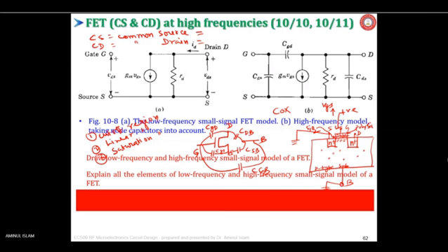If the gate voltage is 0, instead of some positive voltage, then there is no inversion layer, this layer of electrons as you can see here. The layer of electrons gathered under the gate is not there, so current cannot flow from source to drain.